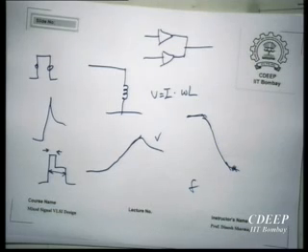Okay, and now the great advantage is because this is current mode, and the voltage is not changing very much, once the current enters at one node, it can't get out. Where will it go from this wire? It can't boil off. So that current is sure to reach the other end as long as the voltage is not changing very much. It is not charging any capacitors. As a result, you don't need repeaters.